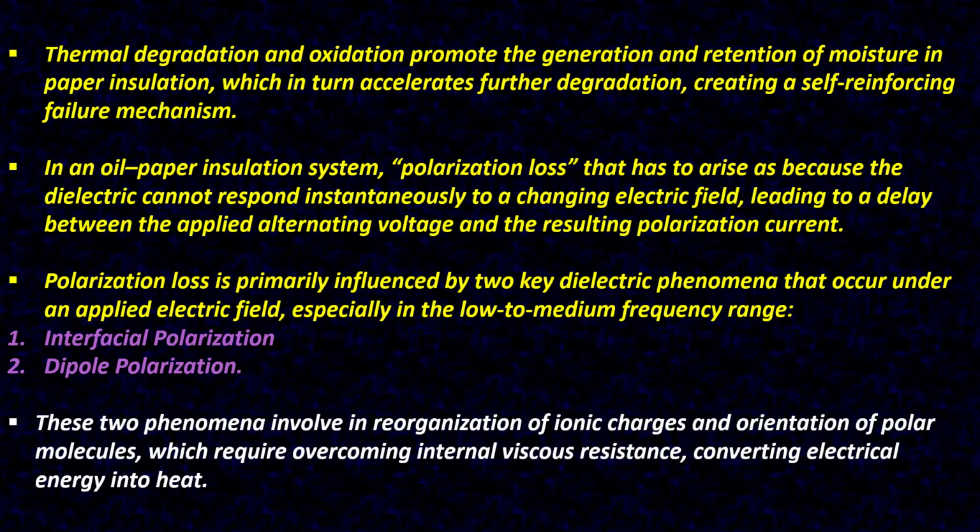Polarization loss is primarily influenced by two key dielectric phenomena that occur under an applied electric field, especially in the low to medium frequency range. One, interfacial polarization. Number two, dipole polarization.